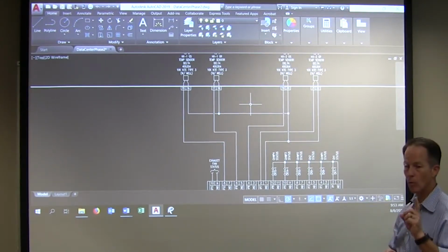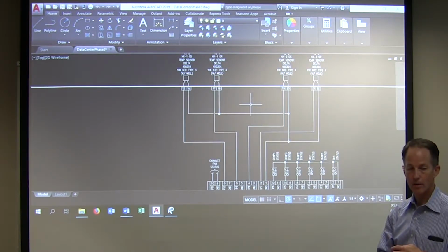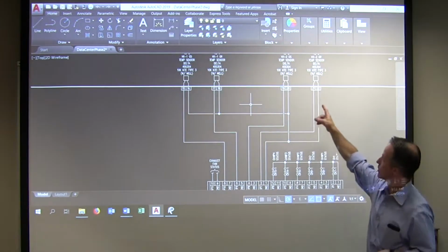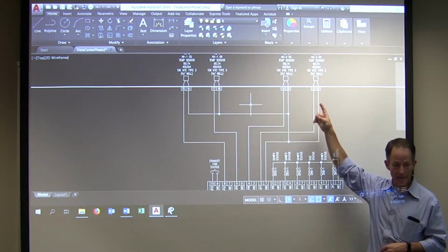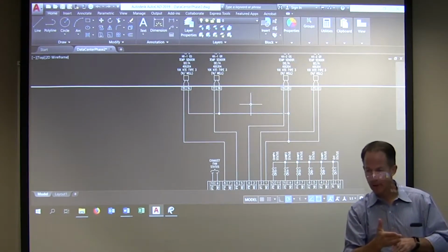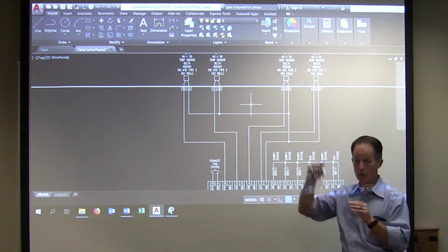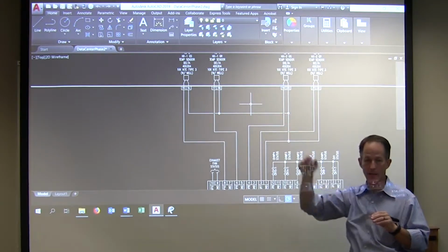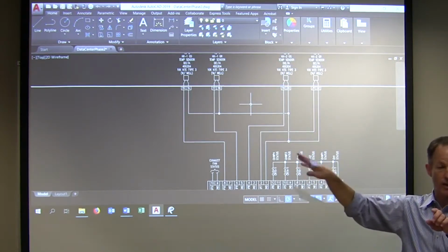Okay. Now, what happens if you have one of the wires nicked and shorted to ground? Will you still read that temperature or that resistance? No, I don't think so. Okay, so this wire, is it a shielded wire? It's non-shielded. So there's really no path. If I'm touching a conduit somewhere, this wire has no path to complete the circuit and short circuit the resistance on the end, right? It's kind of like if I have two wires and I just have a little wire hanging off the side, that wire off the side doesn't do anything.